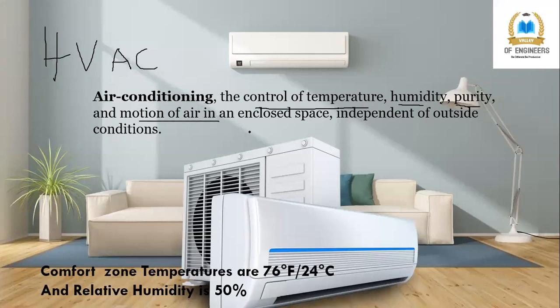These are properties of the air, guys. Remember I told you about psychrometrics. So you control the temperature, humidity, purity, that means you have to keep the air clean, and motion of the air. So four things. The temperature should be, as per ASHRAE standard, around 76 Fahrenheit, or it can be 72 to 76 Fahrenheit, or 20 to 25 degrees Celsius. I will tell you the proper range also. Right now, this is the value.